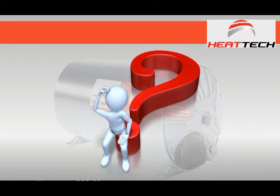And the short answer to your question is no, it cannot be used. The standard says you shall have a vacuum breaker, so you cannot replace it with a vacuum breaker. But non-return valves can be a very, very powerful ally in your whole process to prevent backflow in systems and to prevent water from flowing in the wrong directions. But at no stage may you leave out the vacuum breaker and say, oh no, I'd rather use a non-return valve.